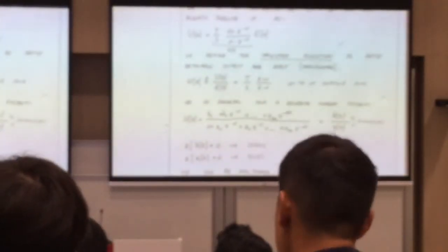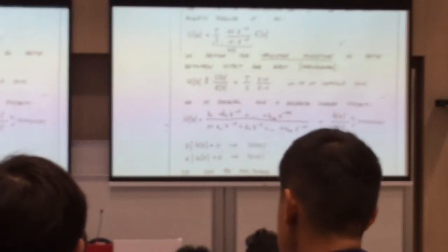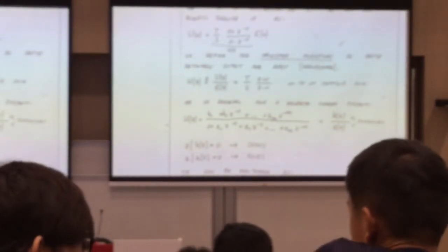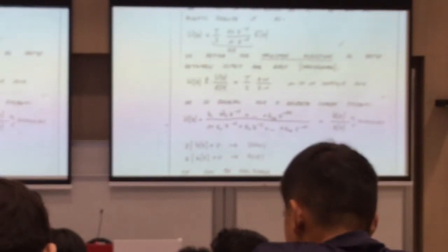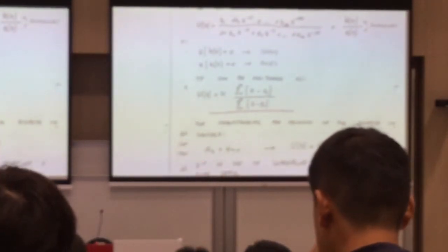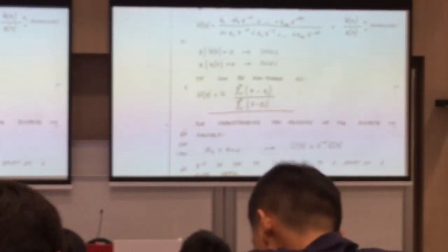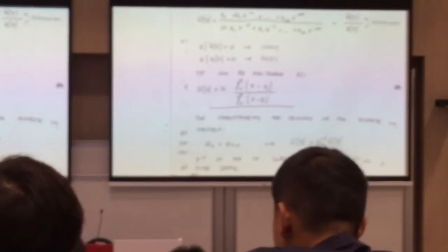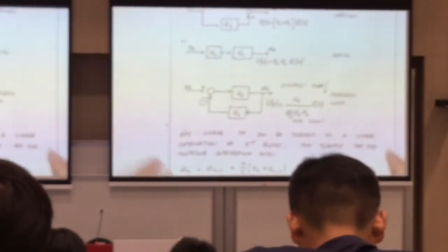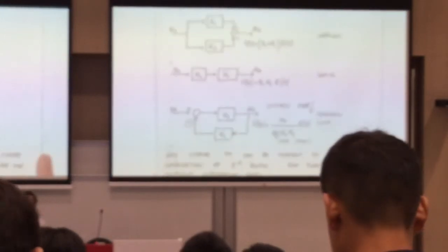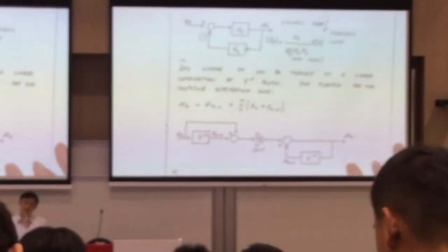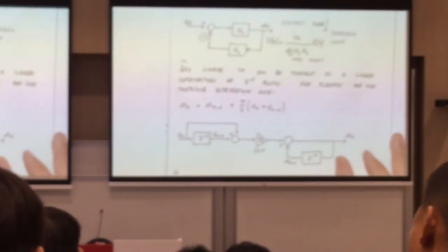After you get this, you get something called the transfer function. After you get the transfer function, you can use its characteristic equation to represent the system. Then you can evaluate where the poles are, evaluate the system stability, and evaluate the system response. Similar to what we reviewed just now, you also have the pole form and zero form. Then you do certain analysis in the complex plane. After you get the transfer function, you can also have a block diagram, as in your previous one. So we also did certain exercises on how to represent a difference equation or a Z function.